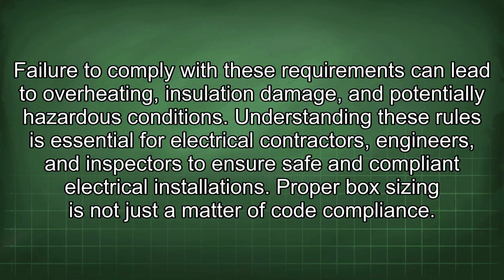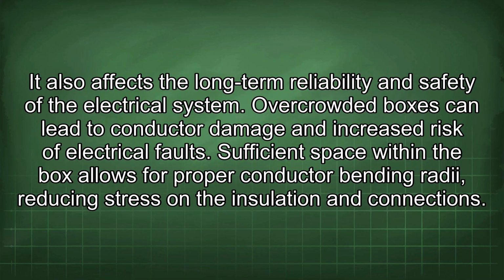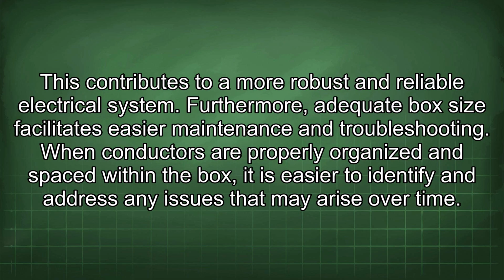Proper box sizing is not just a matter of code compliance. It also affects the long-term reliability and safety of the electrical system. Overcrowded boxes can lead to conductor damage and increased risk of electrical faults. Sufficient space within the box allows for proper conductor bending radii, reducing stress on the insulation and connections. This contributes to a more robust and reliable electrical system.